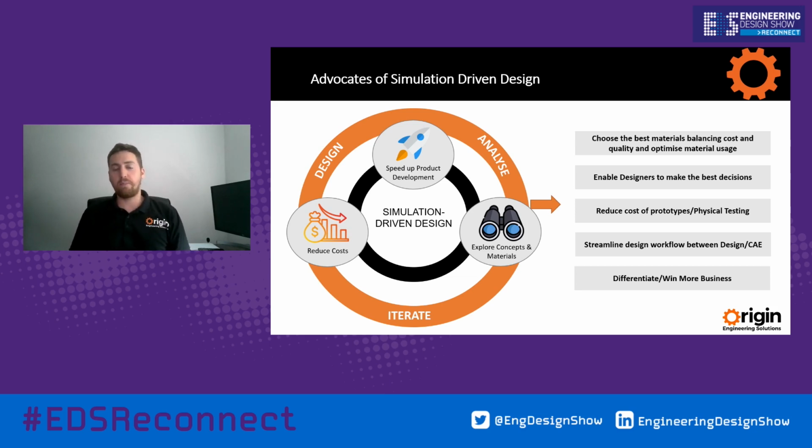Here are a couple of examples of how incorporating simulation early in the design process can help. One could be choosing the best materials. Let's say you are designing a product that's going to be cast, allowing you to quickly study whether this part can be made out of cast iron or out of aluminium, and quickly study the benefits of both materials. This allows you to quickly understand which material is optimal to use, and this can potentially lead to cost savings as well.